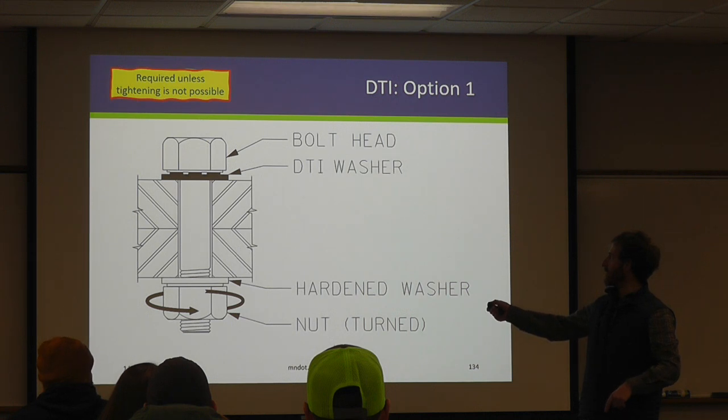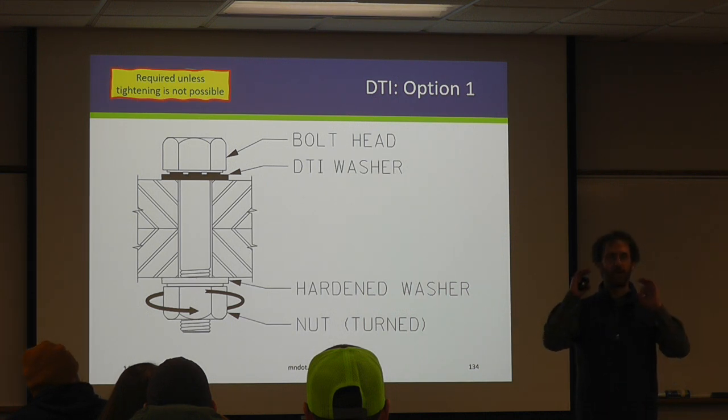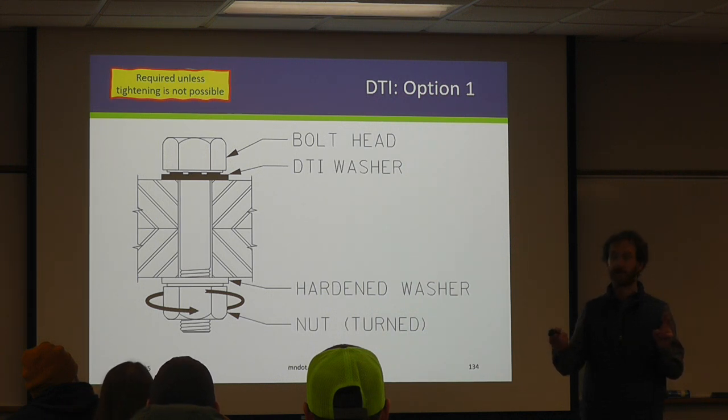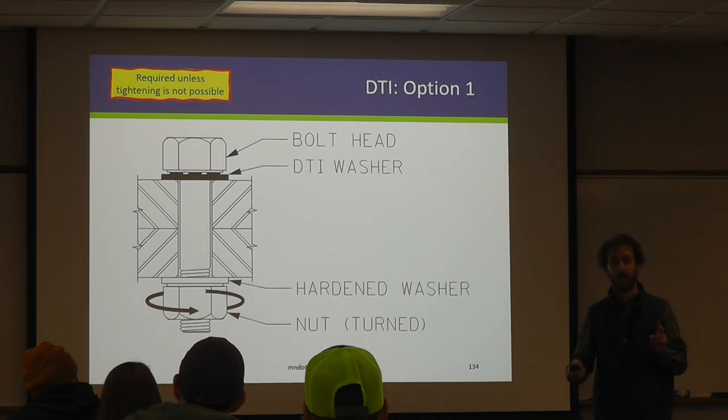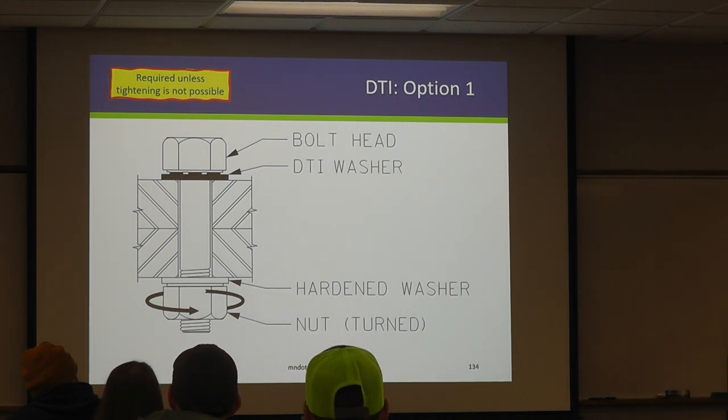I know we don't know a lot about the DTIs yet, but we have provisions where we are not allowed to fully crush them. So if you have a 15-foot tall web, can you see your DTI? Someone's gonna hold it up, right? Yeah, you have to have two people, right? And you have to somehow communicate back and forth while you're rattling up bolts, right? Especially if you're using air guns, it's a noisy operation.